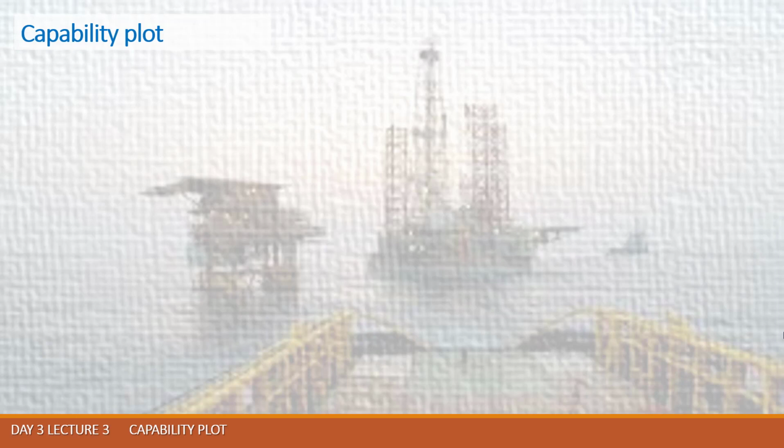These theoretical plots are calculated from detailed information of the vessel's hull and superstructure form and available thrust power. The calculation should use environmental data, sea state, wind and current, appropriate to the area in which the DP vessel is to operate.